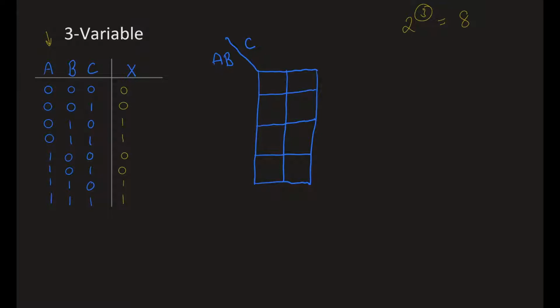Now here's probably the trickiest part of getting K-maps right, and I'm also going to explain why K-maps work. When we go to number this, we number it 0, 0, 0, 1. So far, everything's going good. Here's the tricky part. We next need to go to 1, 1, and I'll explain why in just a second. So 0, 0, 0, 1, 1, 1, 1, 0. And across the top, 0, 1.